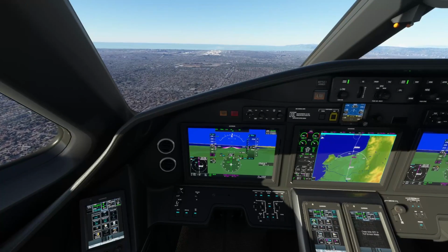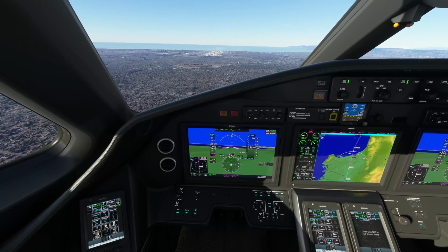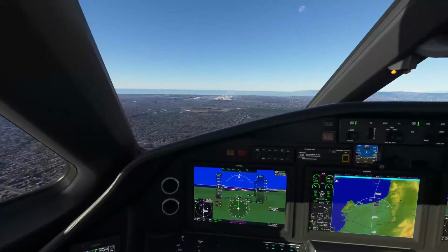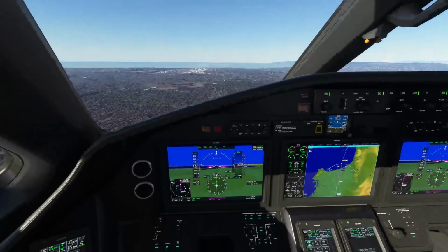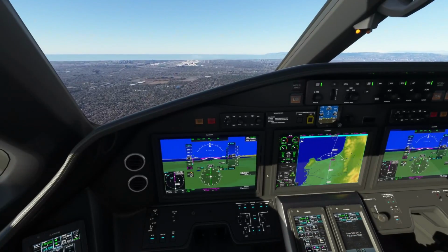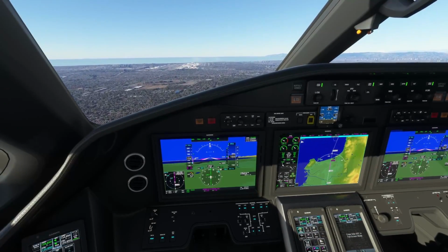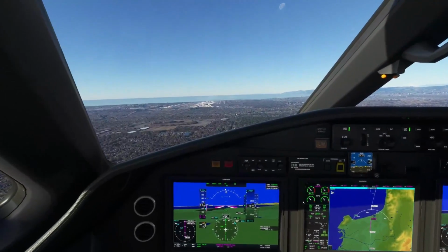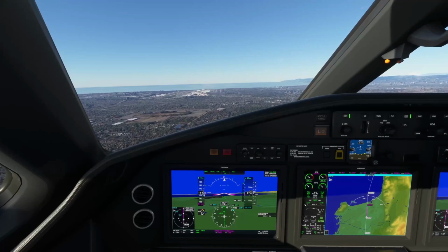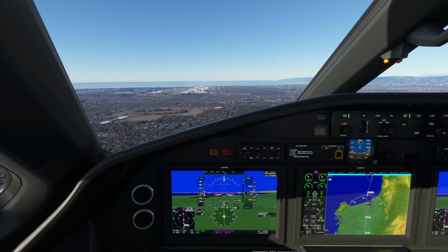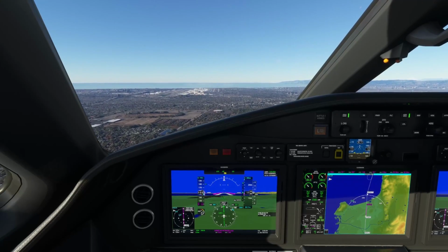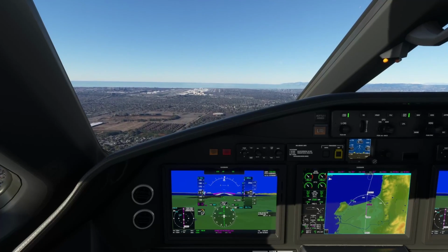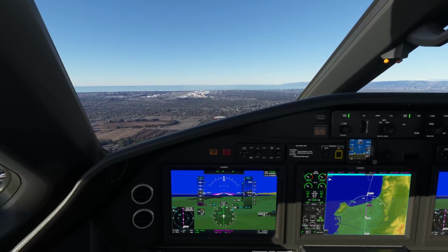Below 200 knots, I'm bringing the gear down. Taxi light on. I'm going to go flaps 2. Speed brake coming in. Alright, disengaging auto throttle, I'm taking control. And that's just because it's fun. The aircraft has certainly proved herself at this point.